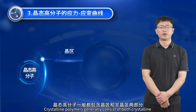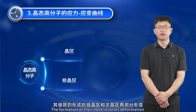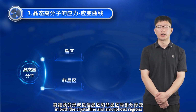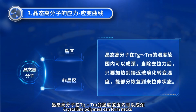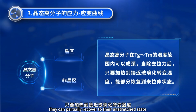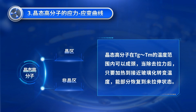Crystalline polymers generally consist of both crystalline and amorphous regions. The formation of their neck involves deformation in both the crystalline and amorphous regions. Crystalline polymers can form necks within the temperature range from Tg to Tm. After removal of the tensile force, they can partially recover to their unstretched state simply by heating to a temperature close to the glass transition temperature.